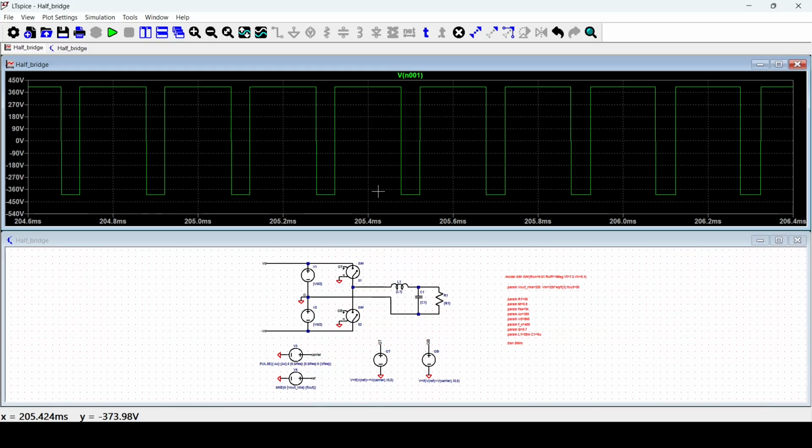So a good design parameter is to have a switching frequency which is high with respect to the output frequency to filter easily the harmonic content, and we cannot have too high a switching frequency, because for these switching circuits and devices, the switching losses in the components are the most dominant at higher frequencies.